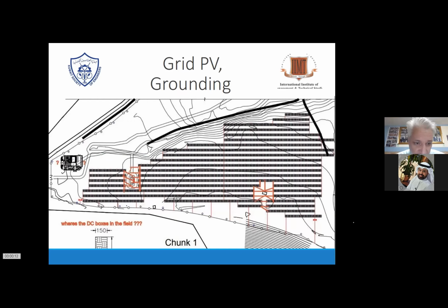The bridges I've done in red or brown are around the transformers. So before, you can see that the small lines from the arrays going down, there was no interconnection towards the inverter. So the inverter slept 1-2 hours longer, which is unnecessary. So it depends where the boxes of the DC combiners are done on site.